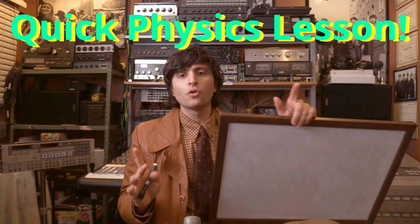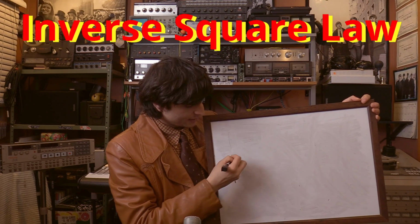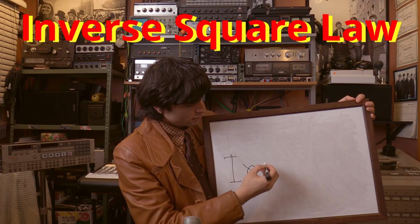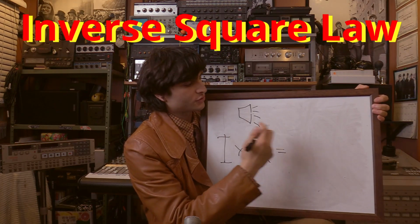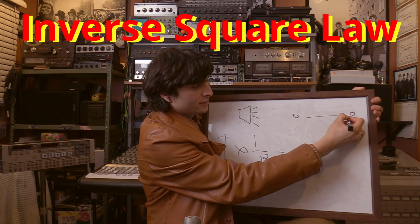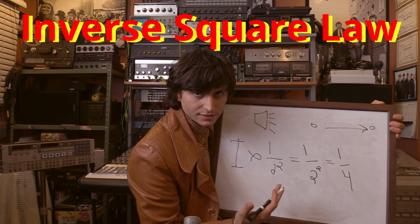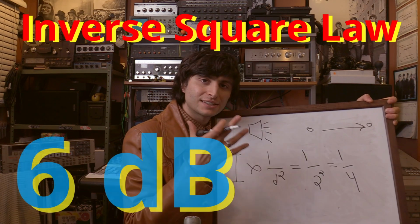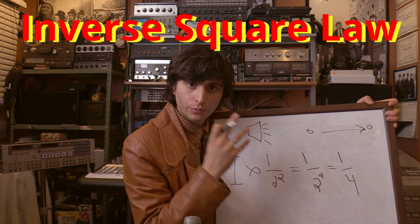And right before we get into the actual design of microphones, I want to go over two basic things about sound that I think is necessary for us all to understand. First off is the inverse square law, and this states that the intensity of a sound is proportional to the inverse of the distance squared. So if we were to have a sound source with a microphone at distance d, and we doubled that distance, we are looking at a fourth of the intensity. In terms of dB, we're looking at 6 dB in reduction for every distance that is doubled from a signal source. Really important to understand.